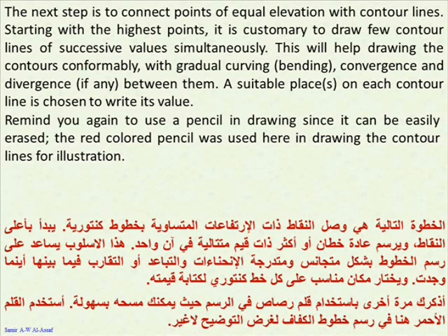The next step is to connect points of equal elevations by contour lines. Starting with the highest points, it is customary to draw a few contour lines of successive values simultaneously. This will help drawing the contours conformably with the gradual curving, convergence, and divergence, if any, between them.